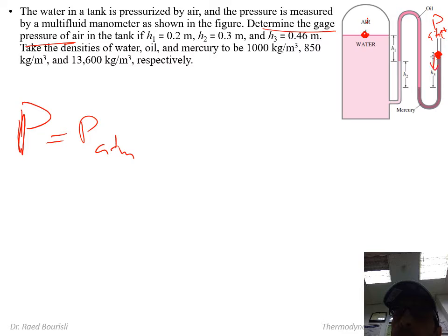If I go down into this fluid, into this mercury, I'm carrying above my head some amount of fluid. So what is the weight of this column of fluid? Of course, I'll work in pressures. I'll just multiply forces and divide by the area. Everything is per unit area, so I'm assuming this is a constant cross-sectional area throughout.